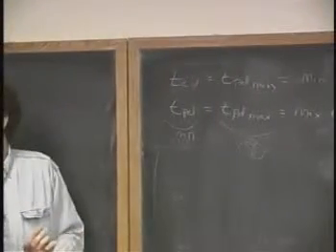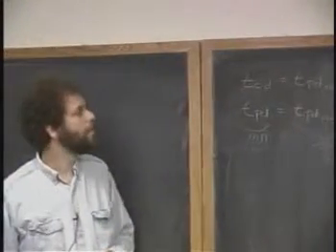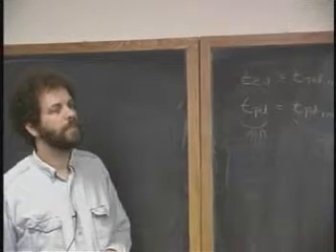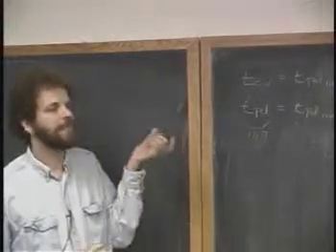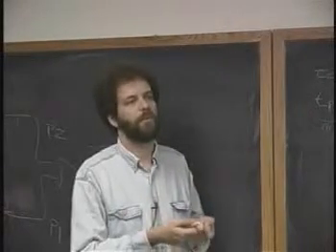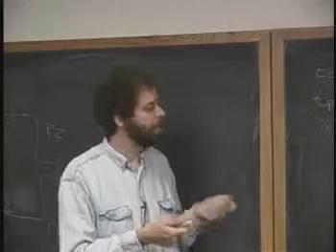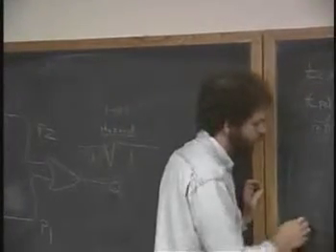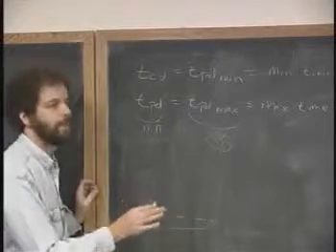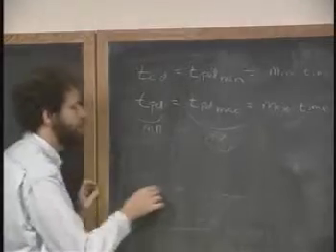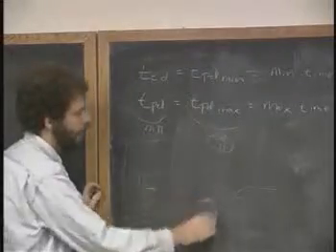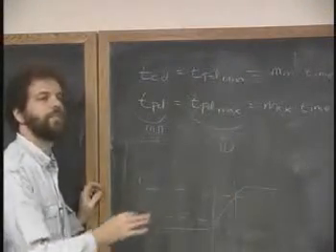If TCD isn't included in TPD, why is it called TPD min for TCD? I mean, it would make sense if TCD was actually part of it. Both of these things are due to the effect of signals propagating through a circuit. The question is, what kind of signal do we mean? In general, a signal goes from being a 0, and then crosses a certain threshold where we say we don't know what it is. And then it crosses another threshold. We say, okay, now we know that it's a 1. And during this time, we say it has an intermediate value that we're not sure of.